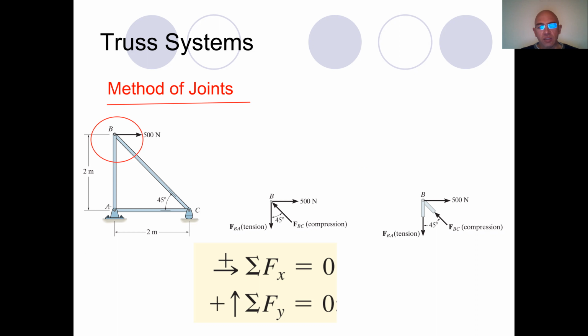Now, this basically means that since we don't have any load all along the member, for example, BC or AB, it carries load only along its direction. And certainly this means that there is either tension, which tries to elongate the structure, or compression, which tries to shorten the structure.